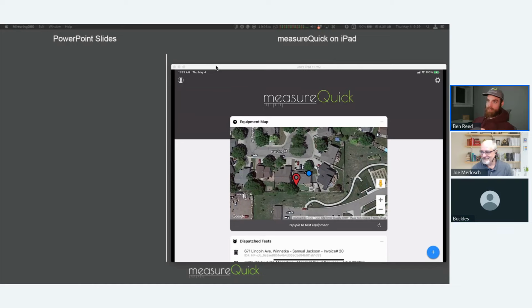One more question just snuck in at the end. John asked: to get a basic assessment, can you use the line pressures and line temps? No, the only thing it's going to give you is a temperature split. So that's a minimal amount of information. Our focus is all nine probes on active reading, with the system on, and that is our fundamental requirement. You can see that a little bit of information could only lead to improper diagnostics.